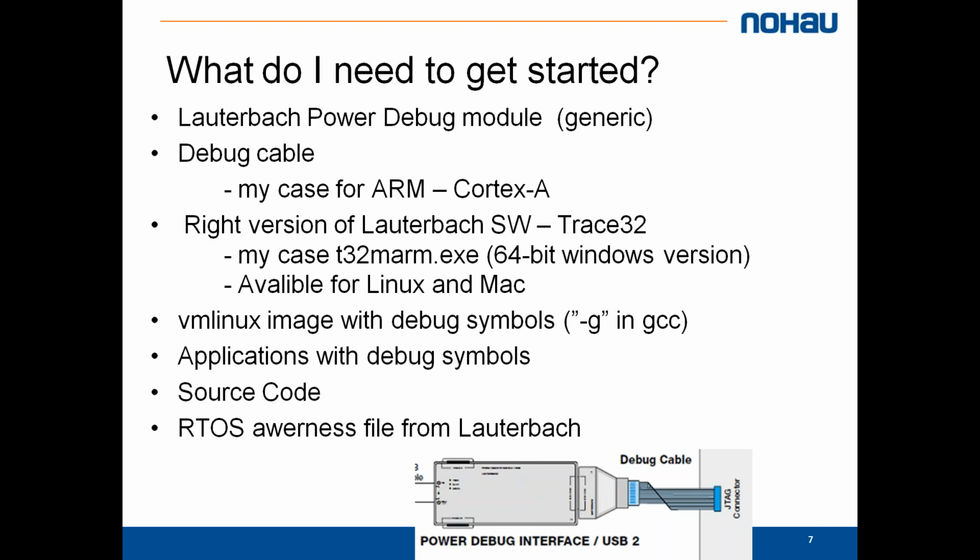And since I'm using Linux on my target, I will use one of the RTOS awareness files from Lauterbach. This is available for more or less every RTOS that you might need to debug on your embedded system.